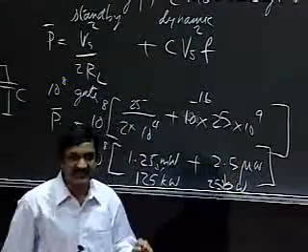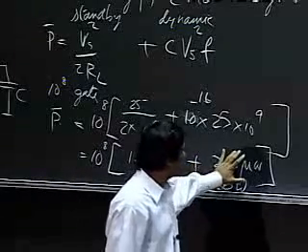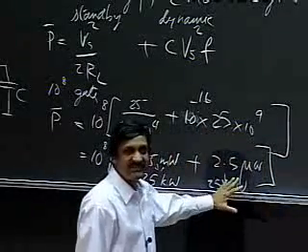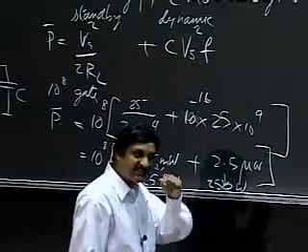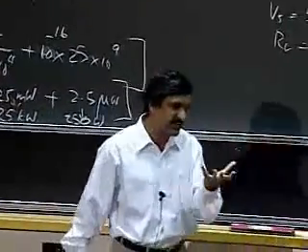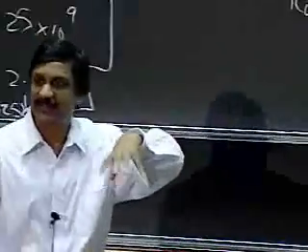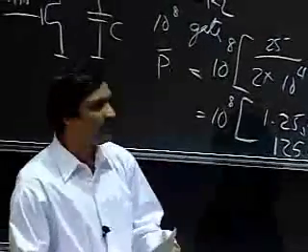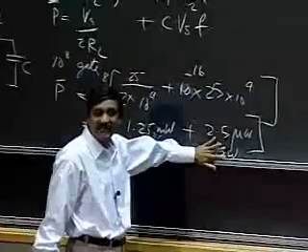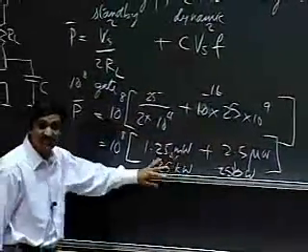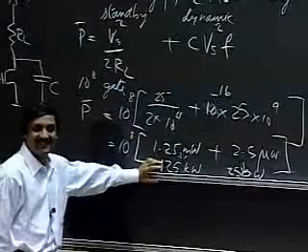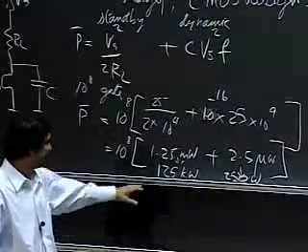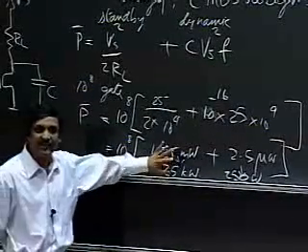Okay, the 250 watts is manageable. It's still high. And just so you don't think that this is unreasonable, when the Pentium 4 first came out, it was consuming 170 watts of power. You should see the heat sinks on there. There's actually a huge heat sink with a fan built into the top of the heat sink. Today it's down to more reasonable numbers like 100 watts and so on. But when it came out, it was in this range. So this is high but not unreasonable. But this, of course, is totally wacko. You may imagine carrying a laptop around and the sucker is blowing 125 kilowatts. So that'll be fun. So clearly there's something wrong here.